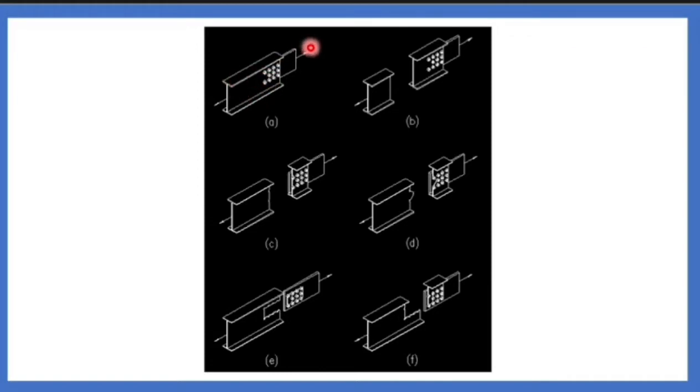If you are having two plates which have been connected by bolt, if you are tensioning this member, gross yielding is not acting at the joint, it is acting in the member at any section. This is called gross yielding. Net section rupture. Why? Because the rupture is between the bolt holes, hence it is called net section rupture. It might be like this or it might be like this. You can see the connection. At the end of the connection, the failure occurs. Block shear failure. And this is block shear failure for plates. If you are providing angle section, this angle member, your block shear will be in this mode.